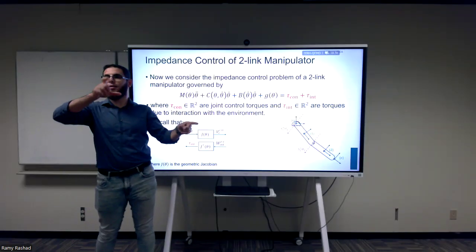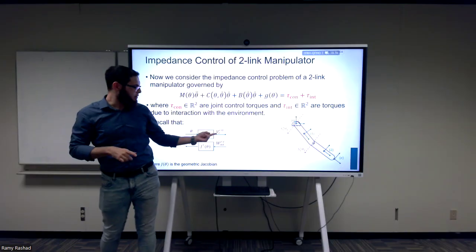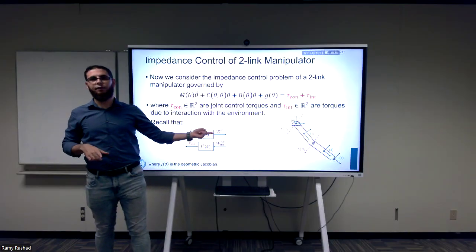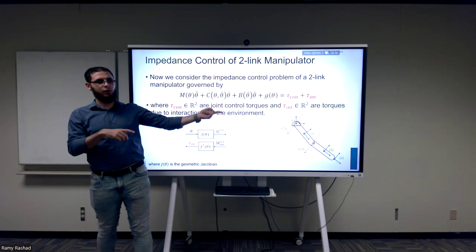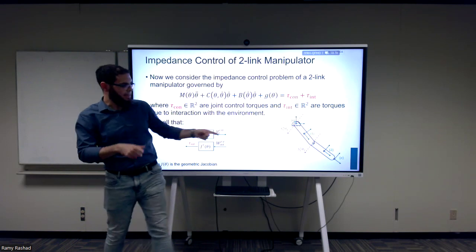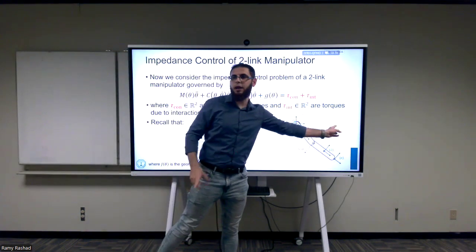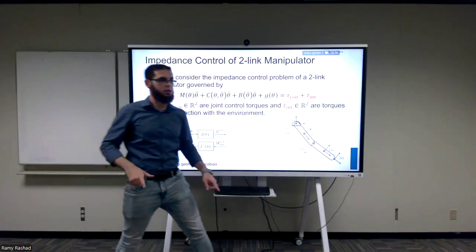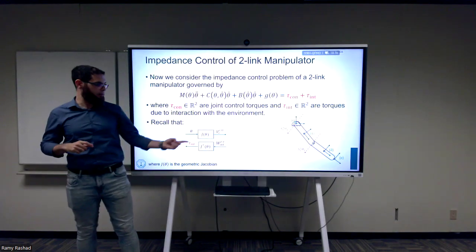When I move theta 1 and theta 2, the end effector will have a velocity. It will have a whole twist. Because this is in 2 dimensions, it will move in the x direction, and in the y direction. It will also have some sort of angular velocity. I can have these 3 motions of the end effector.